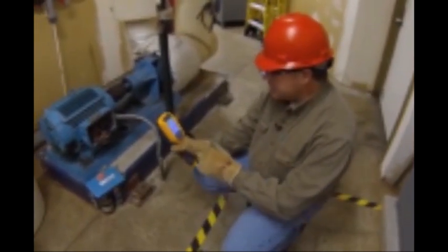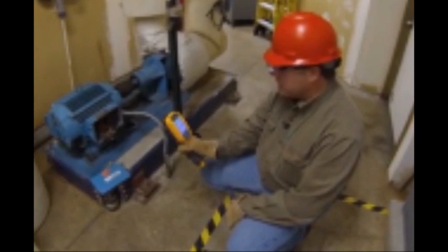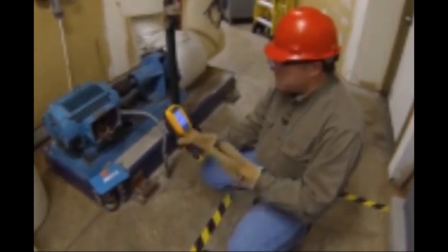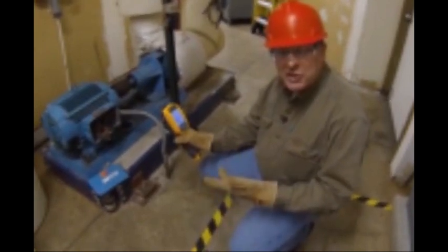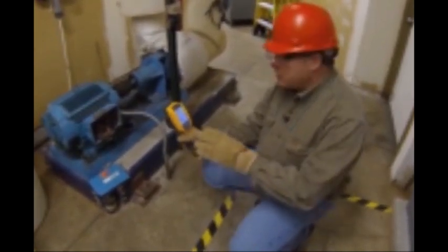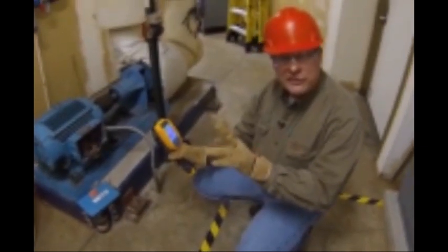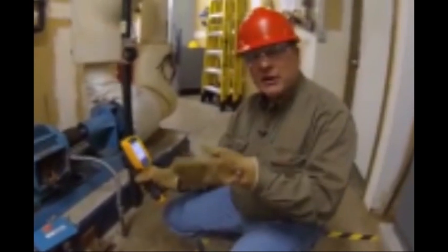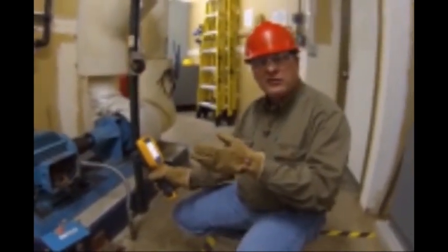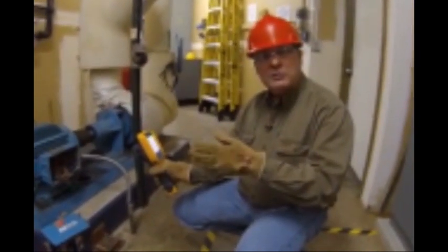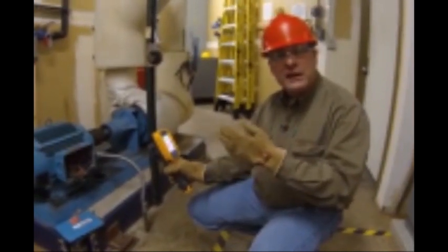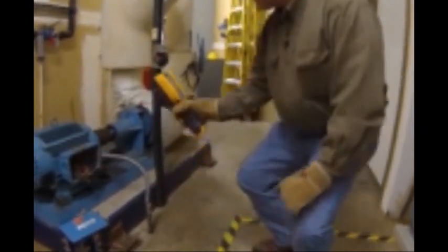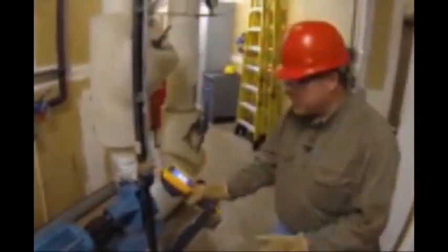a look at those. I'm also looking to see if there's any overload situation on any of the lines. I'm not seeing anything there. You know, a single phasing motor may be operational and may be working, but you're going to see two of the phases significantly warmer than the one that was shut out, okay? It'll be a lot cooler, and that motor will start overheating. It will actually draw more power just to try to keep running. So definitely look out for things like that. No issues there.